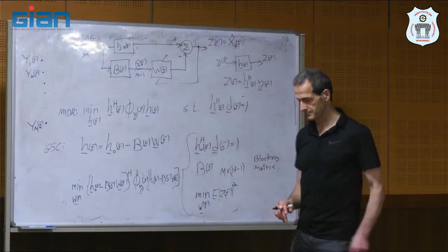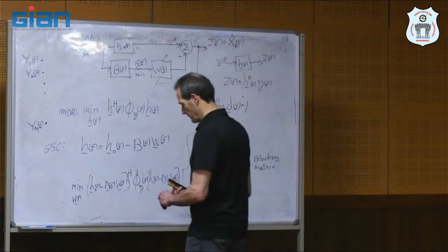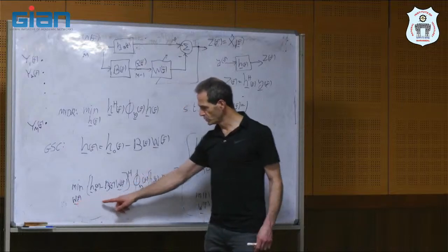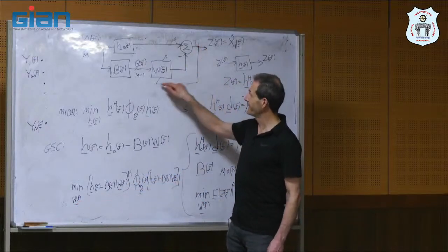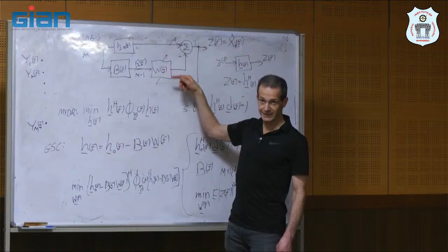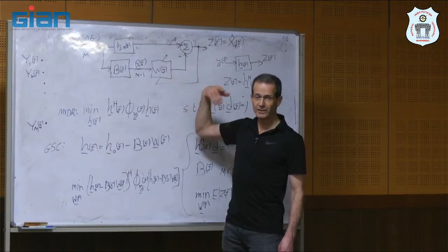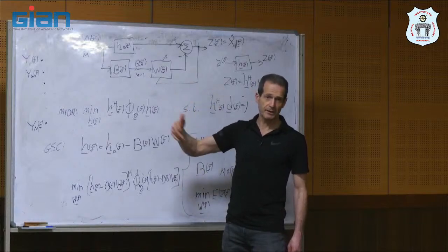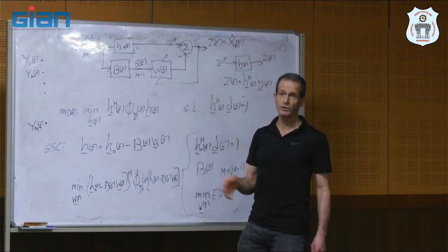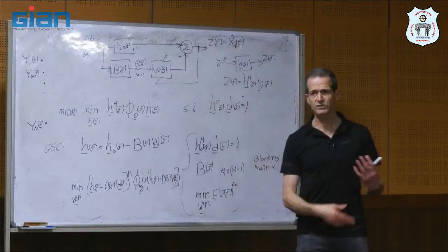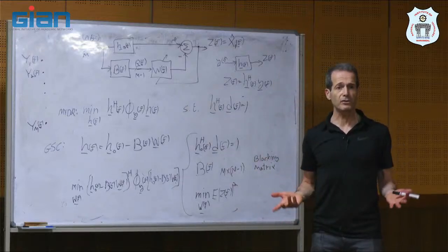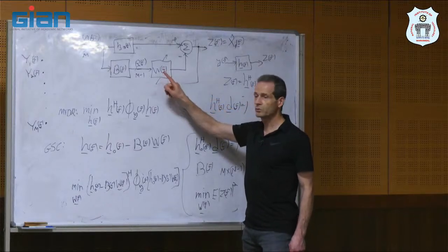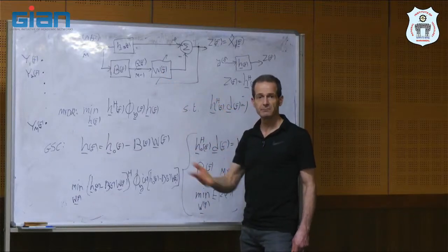Very nice. The major advantage is that to find the solution to minimum variance, we use adaptive filters. So all the methods for adaptive filtering, like LMS, least mean squares methods, normalized LMS, and RLS, we can use for W. So we can do it online, in real time.